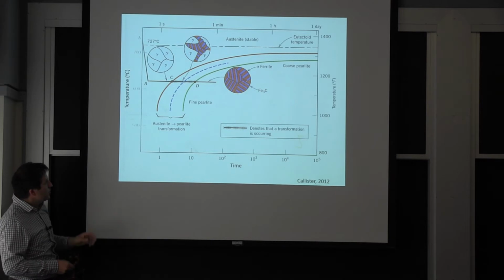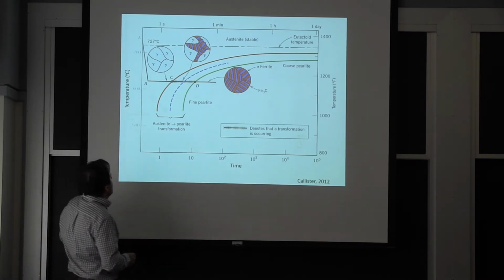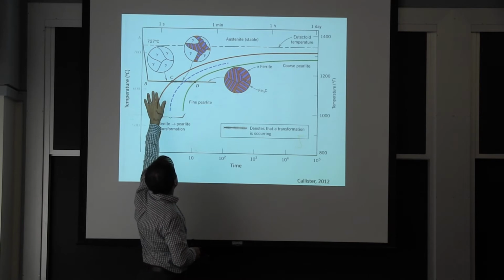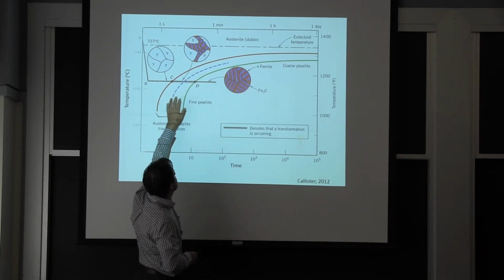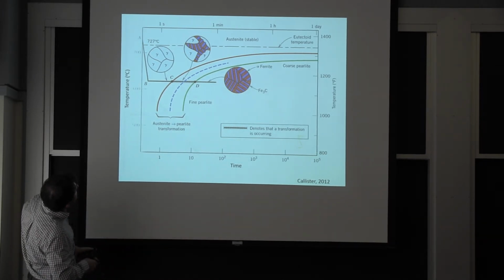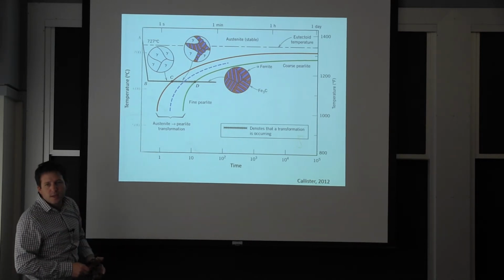If at lower temperature, it's more intertwined, much thinner layers. So this tells you, okay, I'm trying to go from my austenite to the pearlite, the equilibrium phase. It will take a certain time, and this is how it's going to go. You can see it in that schematic. It is starting from the grain boundaries and moving inside the grains.